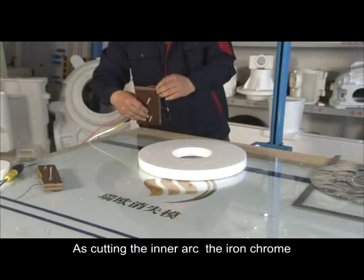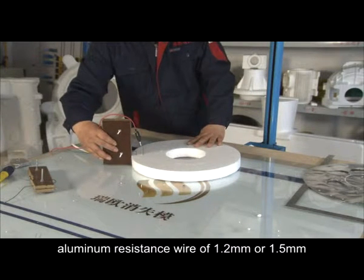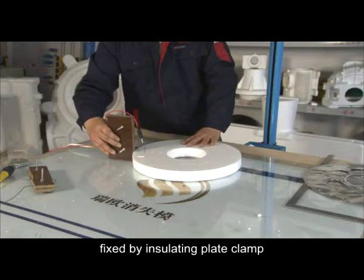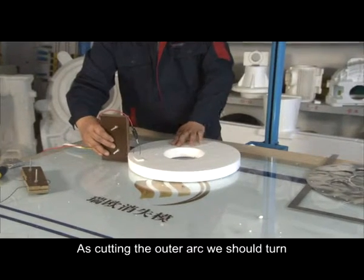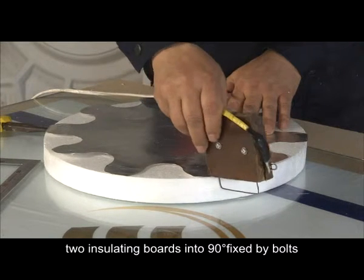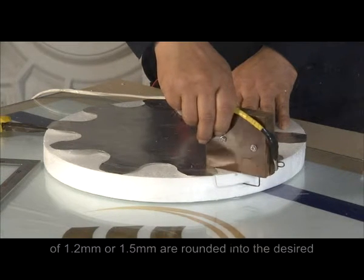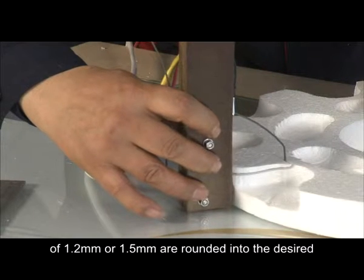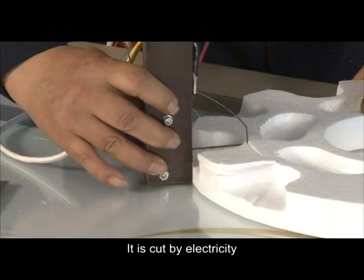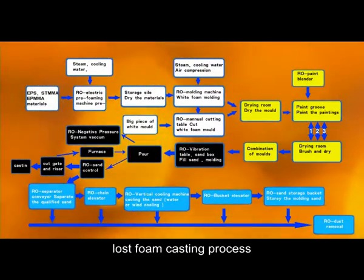As for cutting the inner arc, the iron chrome aluminum resistance wire of 1.2 mm or 1.5 mm is rounded into the desired inner arc. Fixed by an insulating plate clamp, it is cut by electricity. As for cutting the outer arc, we should turn two insulating boards into 90 degrees, fixed by bolts. The iron chrome aluminum resistance wire of 1.2 mm or 1.5 mm is rounded into the desired outer arc, fixed by an insulating plate clamp. It is cut by electricity. The introduction above is the white area of the lost foam casting process.